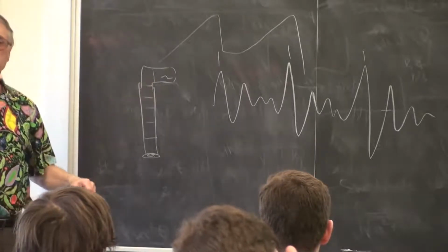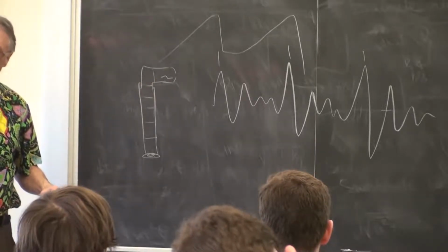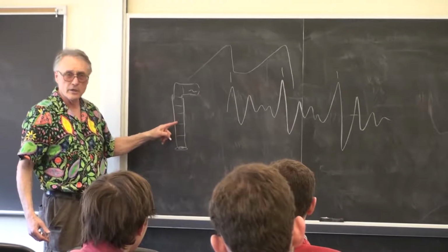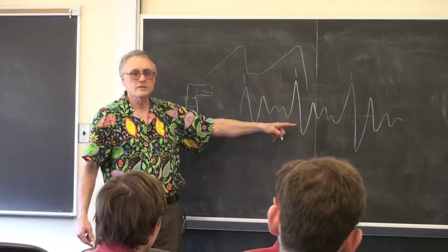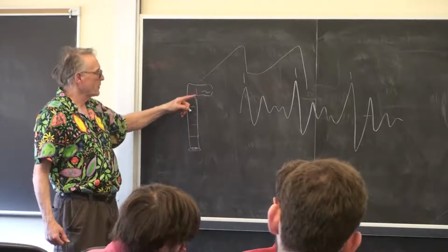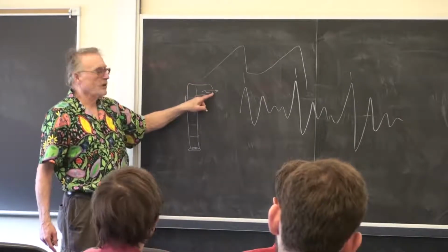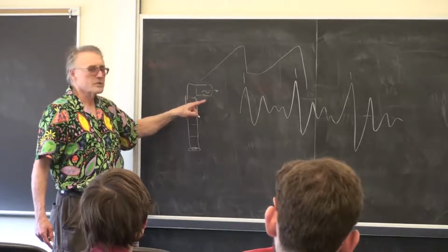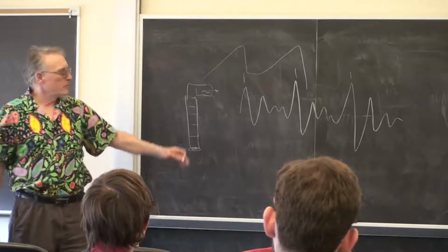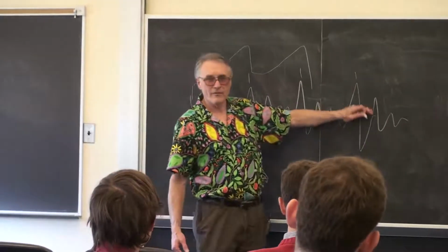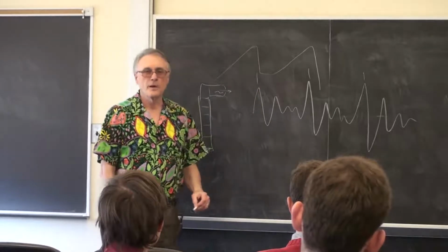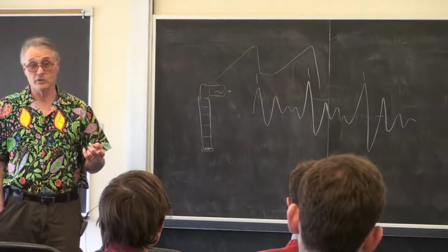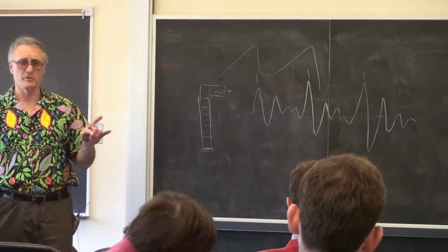And what the tongue does is to change the cross-section of the resonator. When you move your throat, it changes the cross-sections down here. And the way you form these waveforms is by changing the structure of your throat. But there's also some hiss generated off the lips, some further back. So there's a couple of noise sources that have to be mixed in. And the result is this kind of damped impulse waveform that you have to decode to actually get the pitch. That is completely doable by cross-correlation or other mechanisms. There's a huge literature on pitch determination of voice.